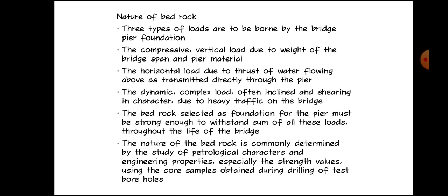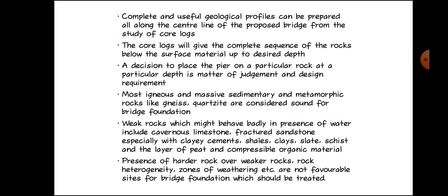The nature of the bedrock is commonly determined by the study of petrological characters and engineering properties, especially the strength values, using the core samples obtained during drilling of test boreholes. Complete and useful geological profiles can be prepared all along the central line of the proposed bridge from the study of core logs. The core logs will give the complete sequence of the rocks below the surface material up to the desired depth.